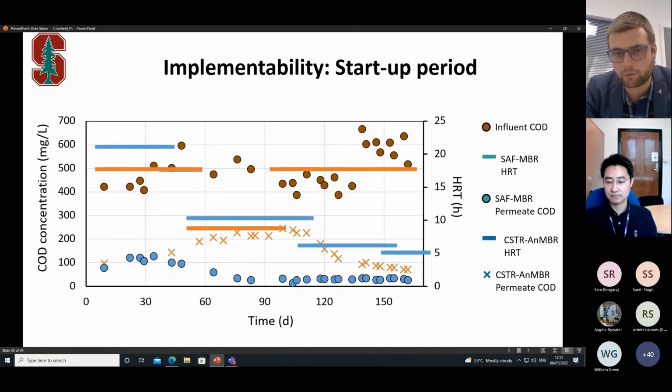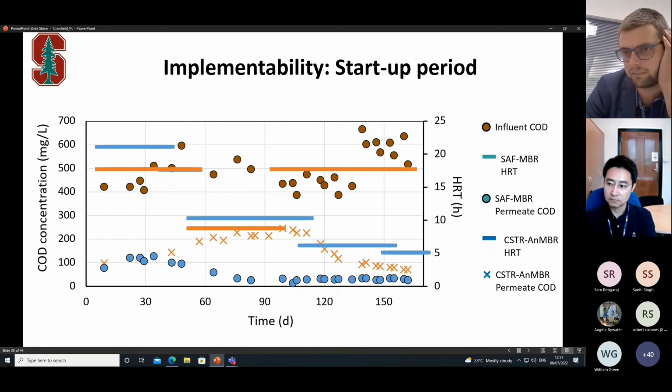I was just a follow-up question really. From Suniti's question, if we were trying to take this work further, we could either try and optimize the pore size distribution of the GAC or the particle size itself to give us more effective surface area. Did you see any clogging of the media, of the GAC? Because traditionally we'd use GAC in a drinking water works, usually pretty far to the end of the treatment works. So it's very interesting that you've applied it for municipal wastewater here.